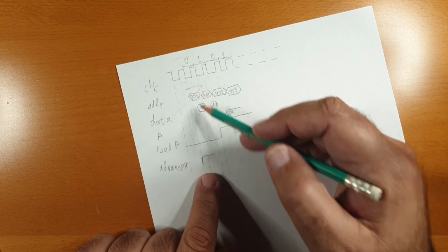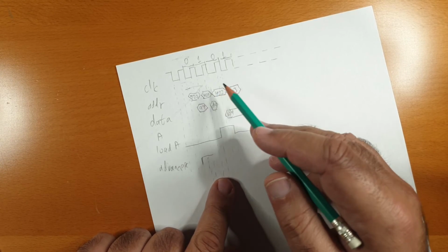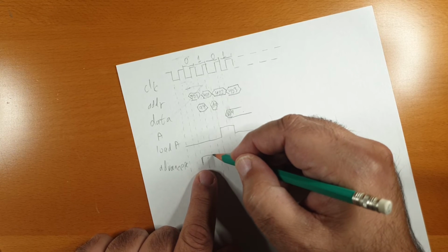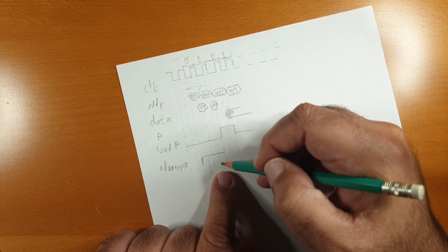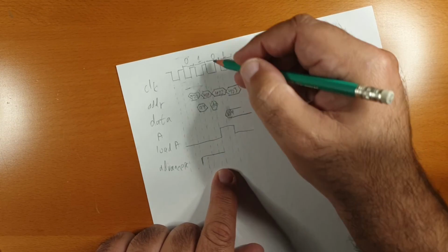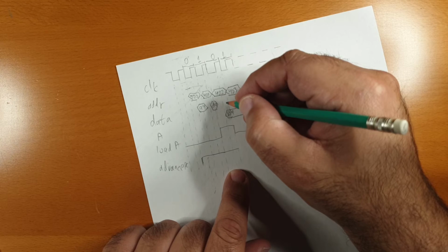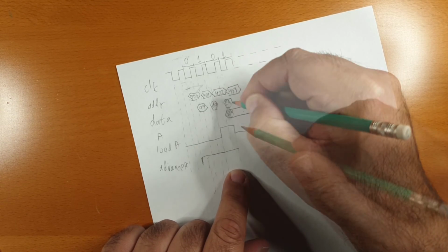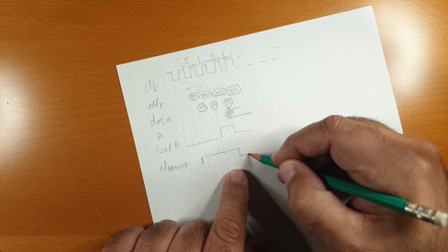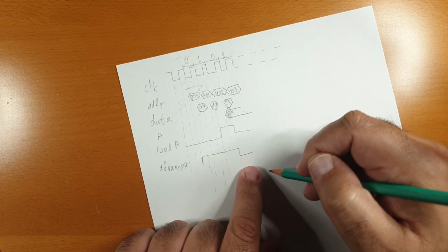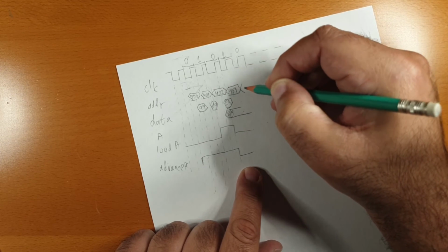However, since we already know we're in immediate mode, we already know that the next cycle is going to consume the data in 401. So we already know that the cycle after that will need to be in 402, which means that we leave the program counter high. Of course, in cycle 1, we call next instruction again, which again sets the advanced PC, which means that in cycle 0 of the next command, advanced PC will remain high. But let's assume this is a NOP, so that would be EA. Since the NOP already knows that it doesn't need the next byte over, it's going to lower the advanced PC, which will cause the next instruction over, which again will be instruction 0, cycle 0 of the instruction, to also be read from 403.